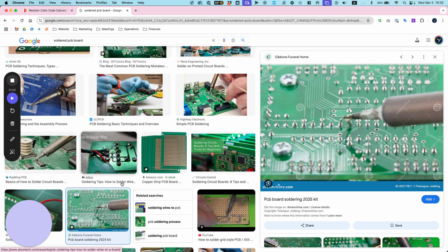When you're done, turn it to 0 and then turn it off right here. But yeah, make sure these don't crisscross. So to prevent crisscross, just put it straight on your circuit first. And then you can turn it on. Or maybe turn it on first, in case the previous person didn't turn it to 0. Turn it on first, make sure it's 0. Then clip it onto your 2 leads, and then slowly, incrementally increase it.